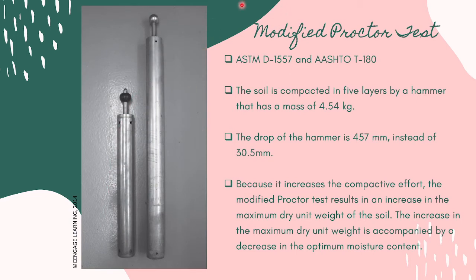Also, we have the modified Proctor test. So, they created the modified Proctor test so that the field conditions, such as when the soil is compacted by heavy equipments or rollers, can be better simulated.